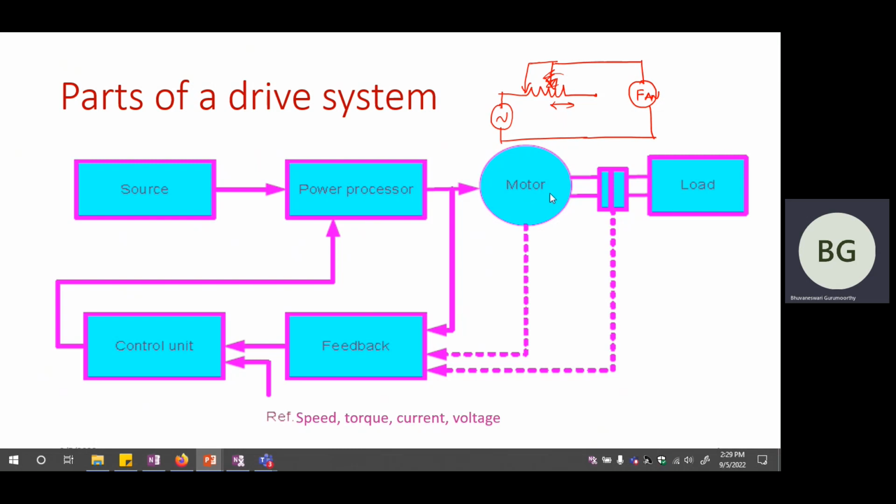The speed is reduced from a higher value to a lower value so that the electric vehicle's wheels rotate at a lower speed, but the torque is increased. So whatever the conversion mechanism, translation to rotation converter, rotation to translation converter, or gear mechanism, both torque and speed may be converted to an appropriate level.